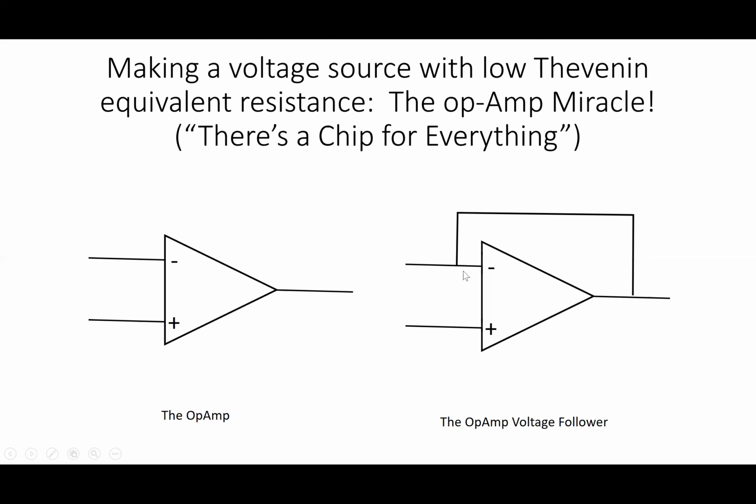It's connected back to the inverting input. And if we go above 1 volt, the inverting input sends the output down. So down it goes. Let's assume it goes down below 1 volt. Now, the non-inverting input is 1 volt. This point connected to the output is below 1 volt, but it's the inverting input. So now it's going to shoot up again to 1 volt.